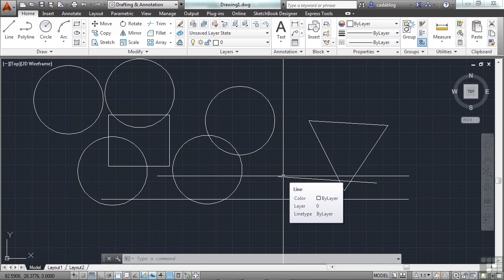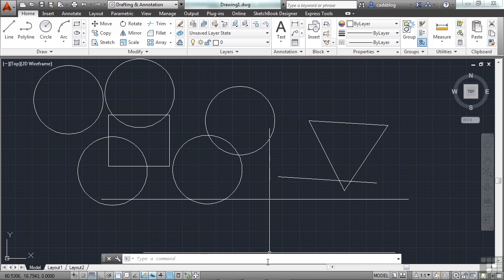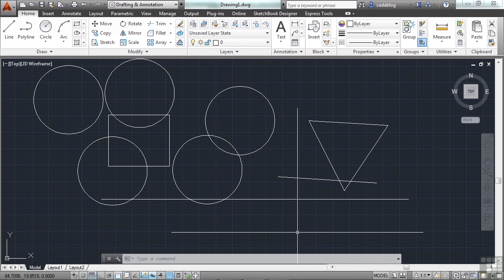Another form of interface in AutoCAD is the palette. We've seen a couple of palettes so far, and we've mentioned them, but we haven't gone into a lot of detail as to what they are. Many managers and tools are in the form of a palette. The command line is a palette. These palettes have tools, commands, or information in them that allow you to manipulate your objects or add to your drawing. One palette that I always use is the Property Manager palette.